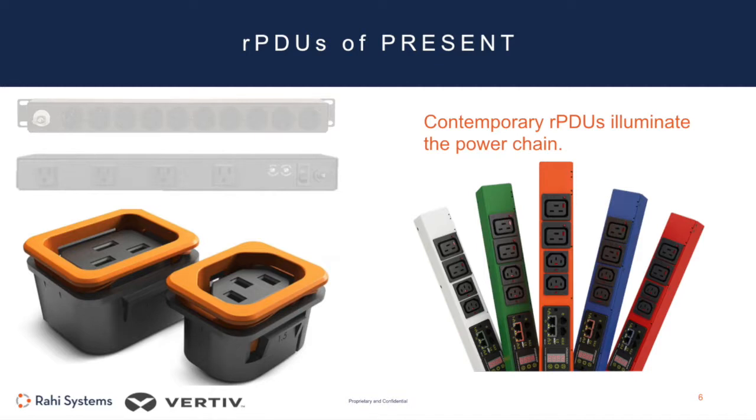These colors can also go to illuminate or illustrate circuit relationships within the rPDU. For some large capacity rPDUs, 6 internal circuits are needed, and as we go up in capacity, you'll have more circuits. So it's important for load balancing to visualize those relationships so that no particular circuit within a PDU becomes overloaded or no particular power is stranded within that rPDU.